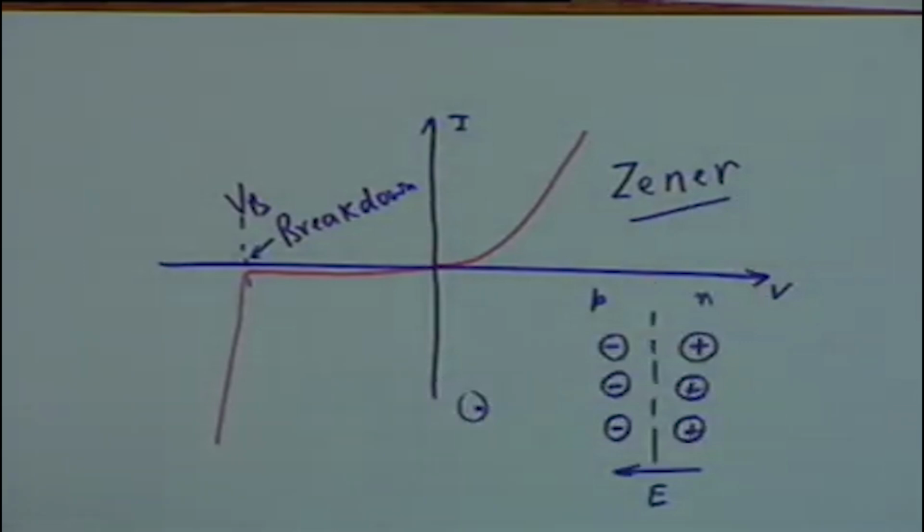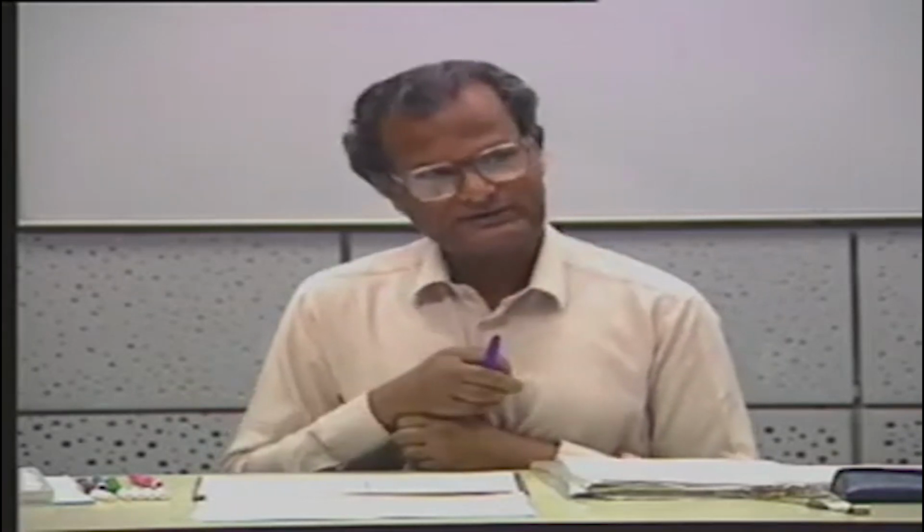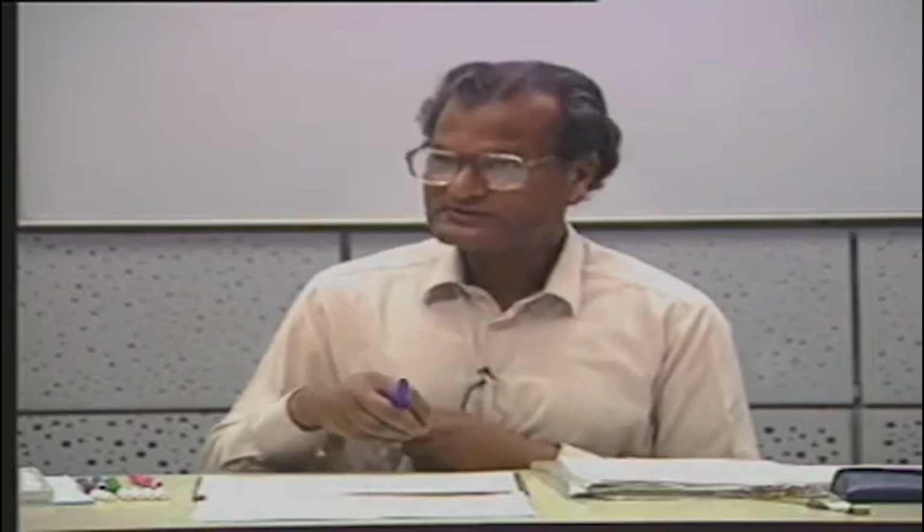It can be precisely controlled, and you can make a Zener diode with almost any breakdown voltage, so long as one point is remembered: as soon as a breakdown occurs, the current increases drastically. Current multiplied by voltage is the power dissipation. So long as the diode does not burn out, if the power is within the dissipative capability of the diode, then the process is reversible.